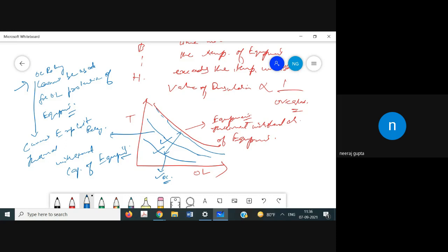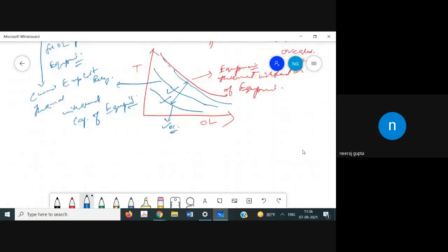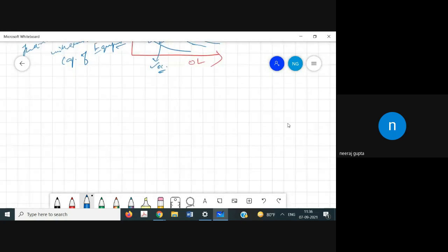So I think this is not beneficial for the equipment as a whole. So in that very case, the overcurrent relay is used for the transient operation, and the thermal relay is used during the overload operation. Now let's have some basic structure of this thermal relay.